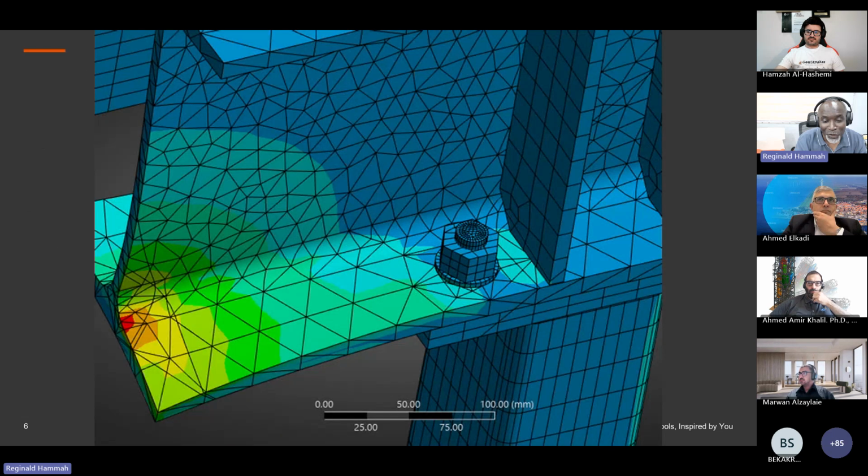Now, this is just a simple picture for structural engineers. You have an I-beam, you have the flanges and the web. It's loaded, it's deforming. You want to know the stresses and deformations of this beam, for example. You can use these numerical methods to do that. So you split up something which is a continuum into these elements. And so we'll see the difference between a boundary element and finite element. But whatever it is, it always involves splitting up your original problem into elements, discrete particles or blocks that interact with each other, and solving some equation.